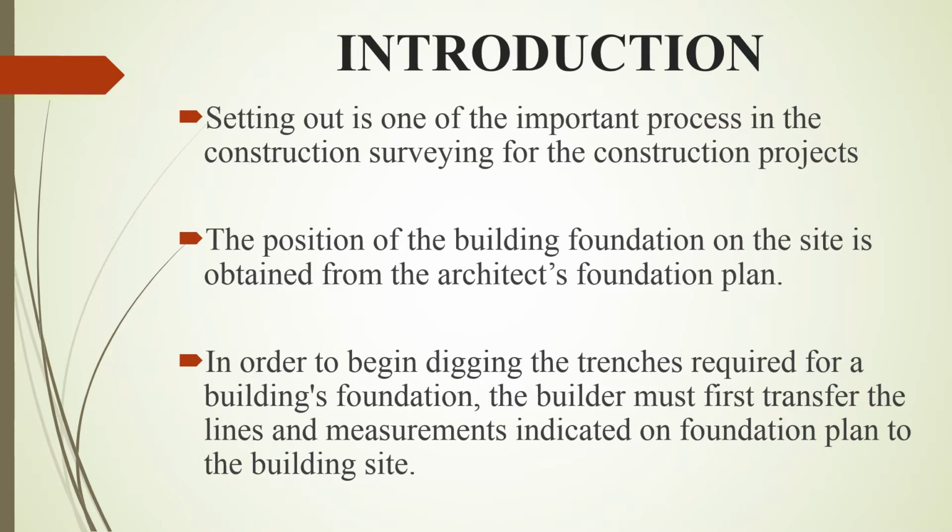The position of the building foundation on the site is obtained from the architect's foundation plan. Once the design of the foundation is complete, a foundation plan is prepared at a suitable scale and the plan is dimensioned accordingly.